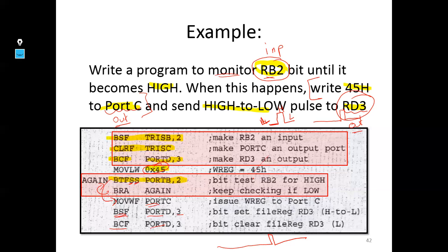Okay, but if you want to read, if you read from the latch, you will read the value that you sent previously. If you read from the port, you will read the value that is in the hardware.